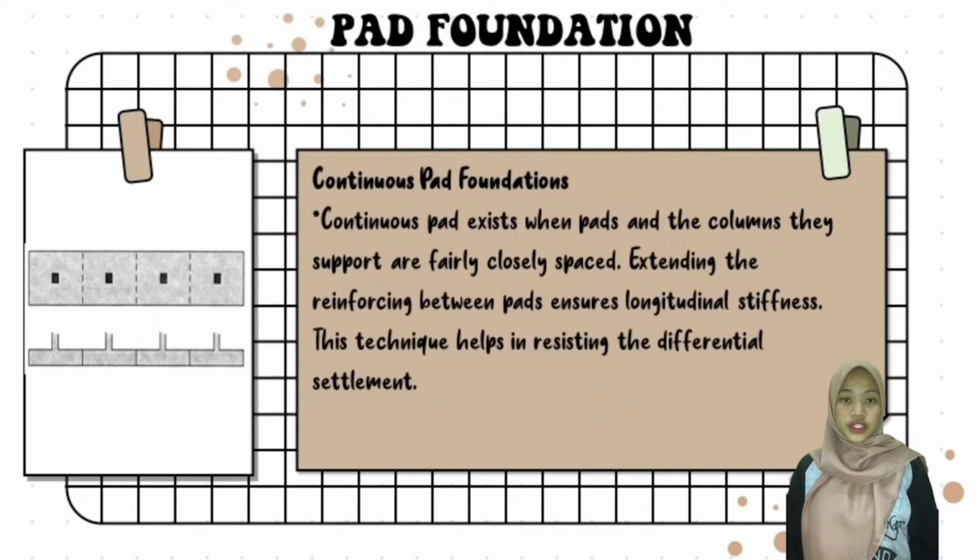Continuous pad foundations. A continuous pad exists when pads and columns support a fairly closely spaced load. Extending the reinforcing between the pads ensures longitudinal stiffness. This technique helps in resisting vertical settlement.